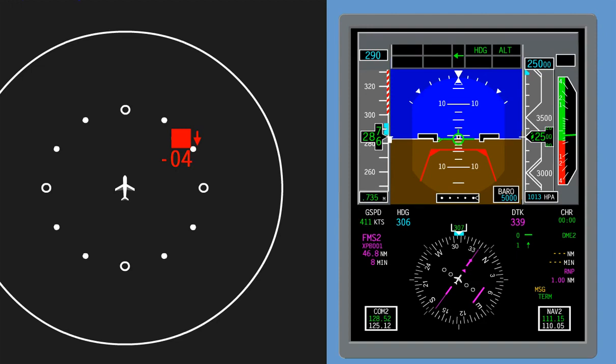When the TCAS detects an RA condition and a maneuver is recommended to increase the vertical separation, corrective RA, Descend. Descend. One or two red trapezoidal avoidance zones and a green rectangular fly-to zone are displayed.